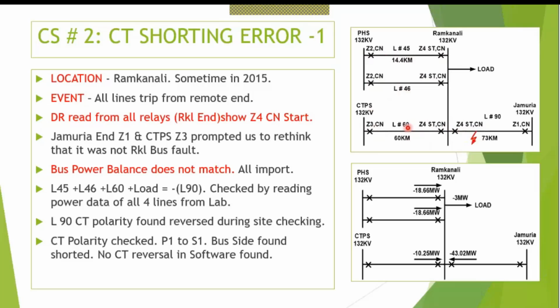So this is multiplying this part of the impedance. And you can also see in this particular case under normal load flow conditions this is a very lowly loaded line. So the fault current contribution from this would have been a bit lesser. So the multiplication of this amount of impedance will affect this one more. That is why, in a real life example, this is coming in zone 3.